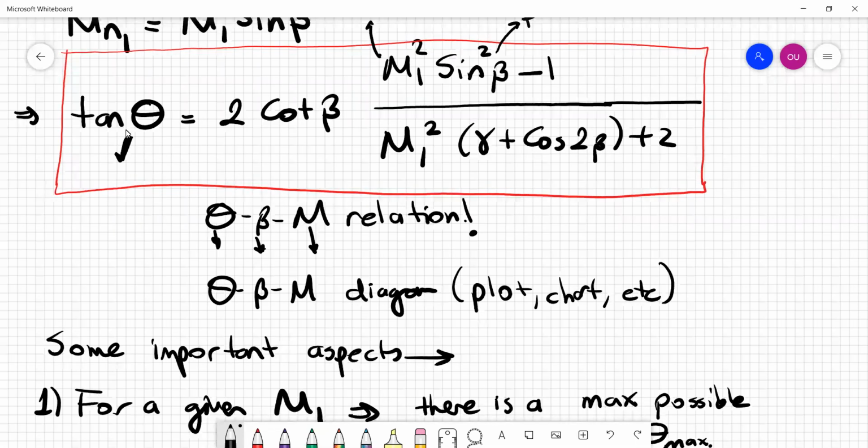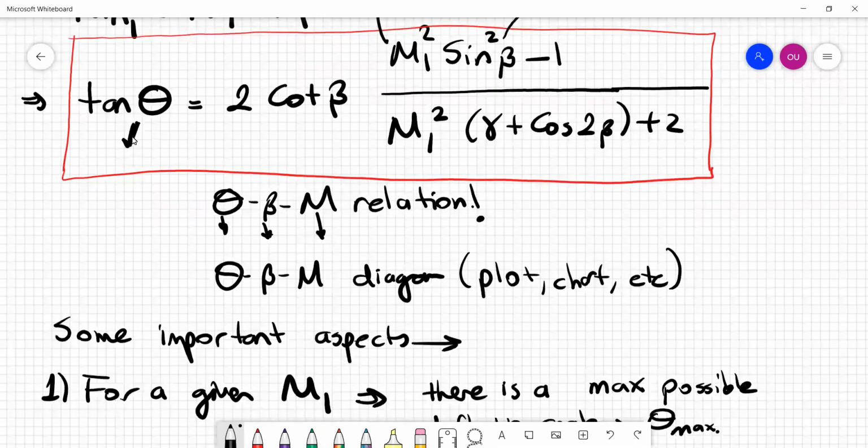By the way, theta is an input, don't forget. We are not only inputting this M1 here, which is your flight condition, this is also an input, this is your geometry. This equation tells us that these two must be consistent with each other, meaning that you cannot just put any Mach number and expect this equation to work. No, you cannot do that.